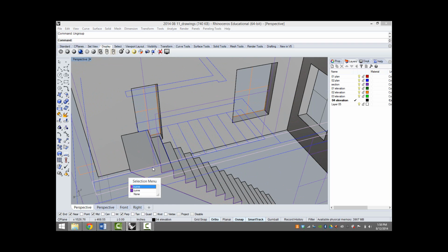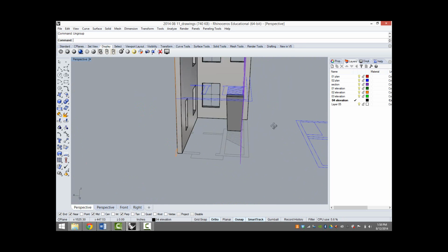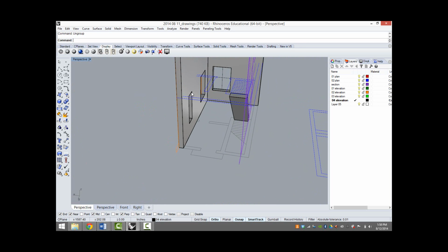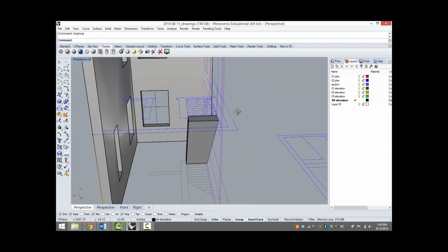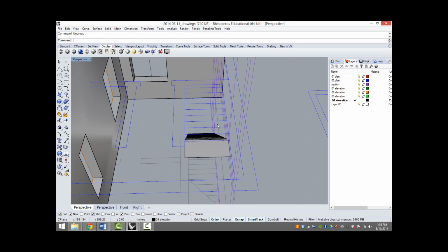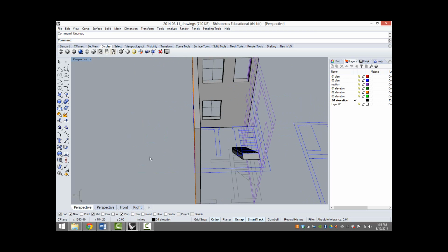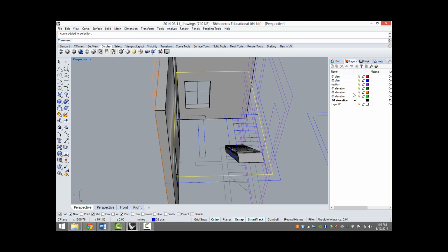And you'll see that we have this situation on the second floor where we don't want to be booleaning too many things because Rhino's going to get confused. Booleaning, for some reason, is very heavy for Rhino. So generally, the idea of the stair, it looks like it's just an open floor plan on the second floor. Generally, the idea is open floor plan with an opening to accept the stair, right? And then we can draw the walls separately. So let's just designate an opening for the stair.